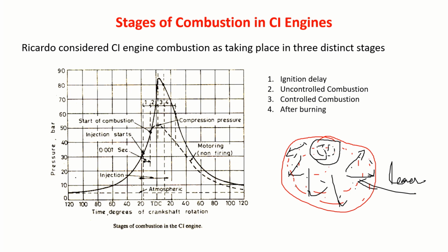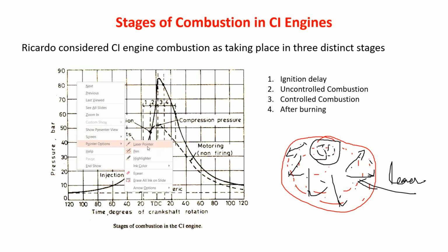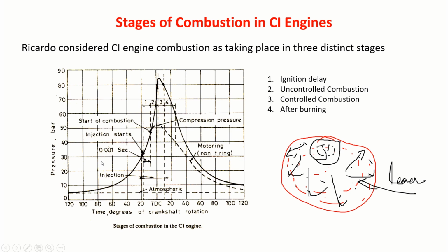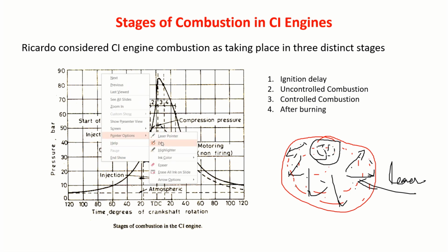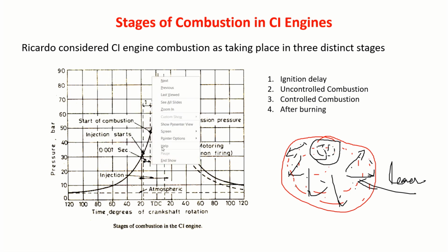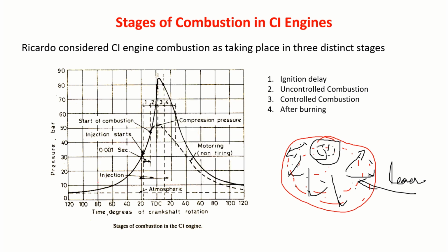So first of all, you are compressing the air like this. You are injecting the fuel. A flame front will appear here. This is what we call ignition delay. In a petrol engine we call it ignition lag. Here we call it ignition delay.